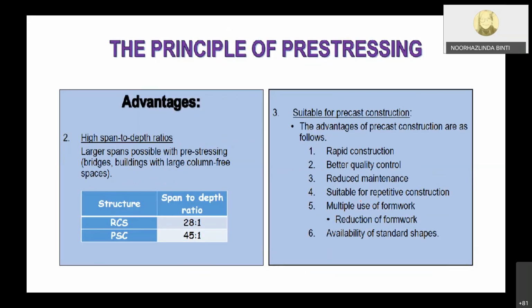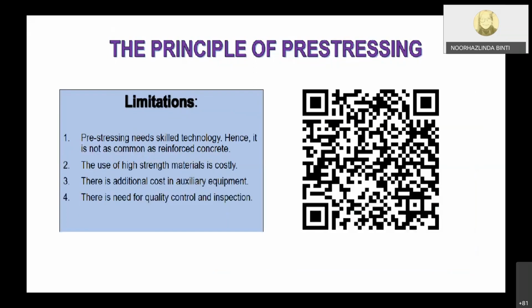Quite good when you use PSC. And suitable for precast construction because of rapid construction, better quality control, reduced maintenance, suitable for repetitive construction, multiple use of formwork, and availability of standard shapes. So that's what the advantages are.